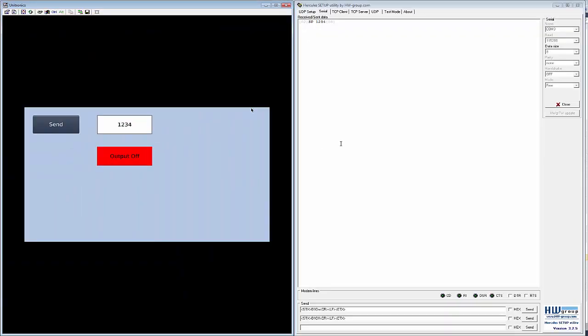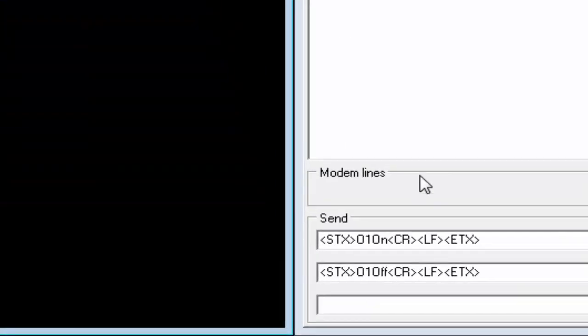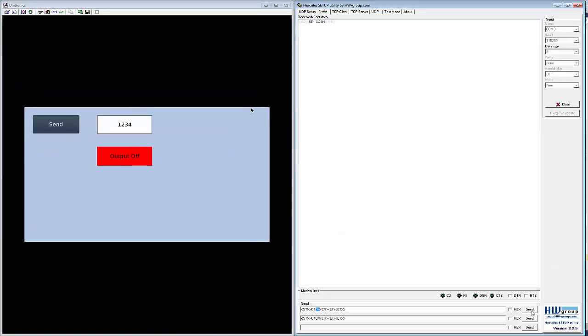Now we can demonstrate the UniStream's ability to receive messages. The hex and ASCII message can be configured and typed into Hercules, which was set up previously. The message must be formatted exactly how it was set up in UniLogic for it to be completely accepted. For this demonstration, I will turn the bit on the HMI screen representing output 1 on, sending the first message with the ASCII text set to on. We can then see on the HMI that that bit was then turned on.